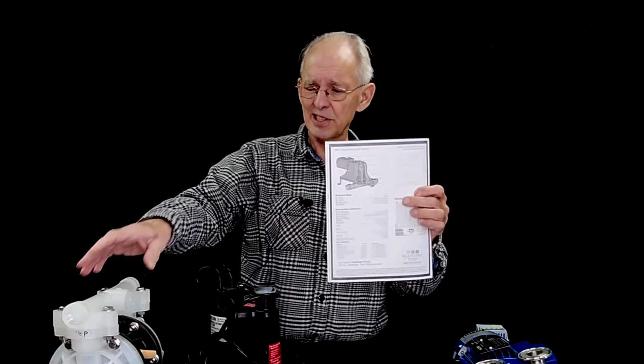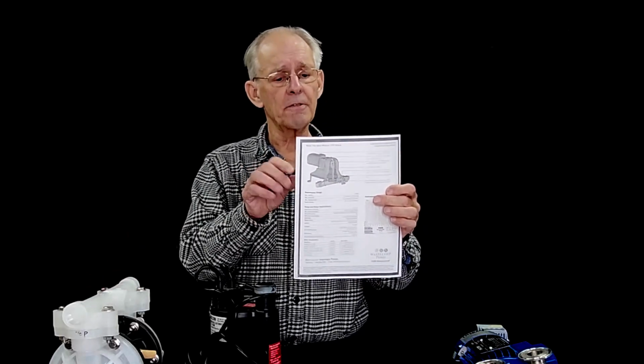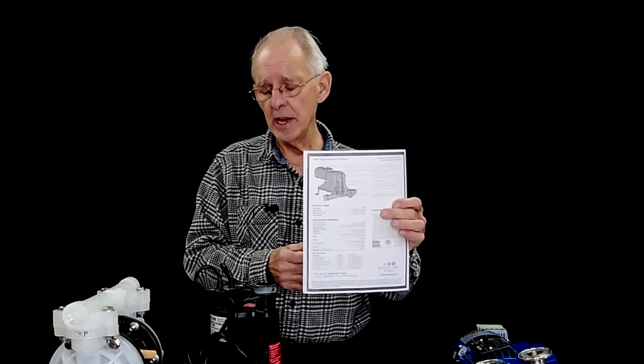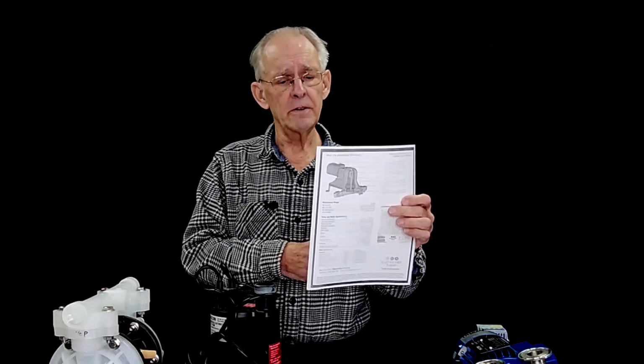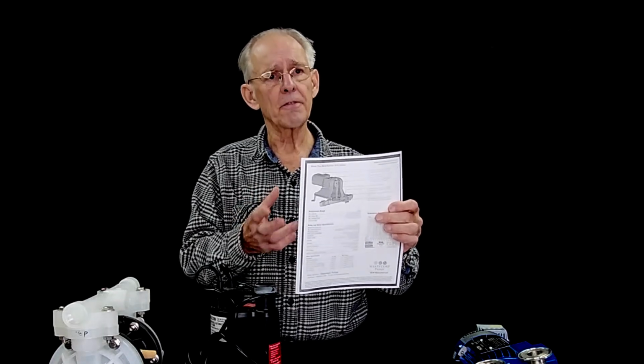This is another positive displacement pump. This is a diaphragm pump that's electrically powered. It's kind of like this, single diaphragm, check valves both ends, and you can vary the speed of it, and it's a single diaphragm. So this has a lot of pulsation. Essentially, you get a pulse, then you get nothing as it's retracting, and then you get another pulse. Whereas with this one, the double diaphragm, the flow is more or less continuous.